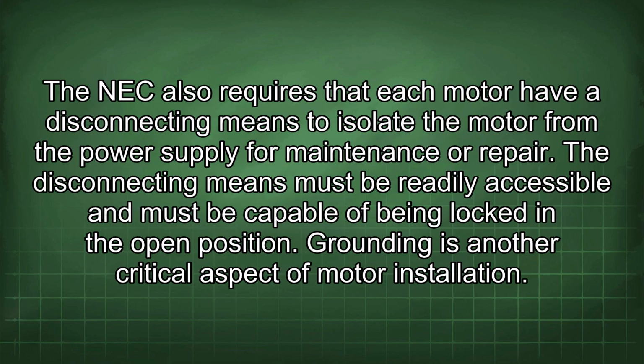The NEC also requires that each motor have a disconnecting means to isolate the motor from the power supply for maintenance or repair. The disconnecting means must be readily accessible and must be capable of being locked in the open position. Grounding is another critical aspect of motor installation.